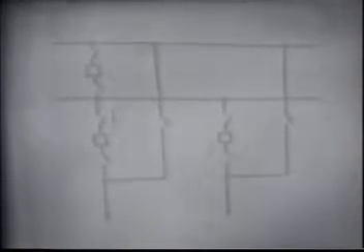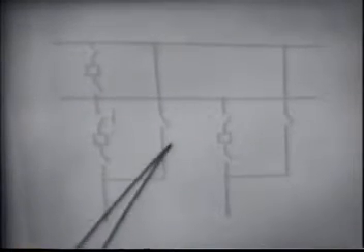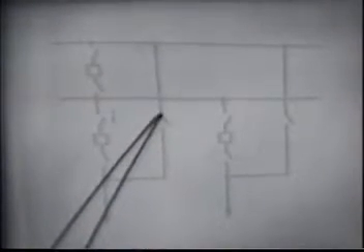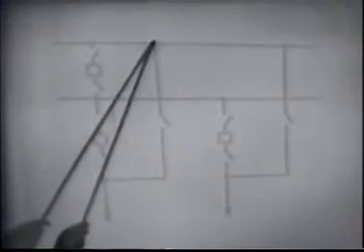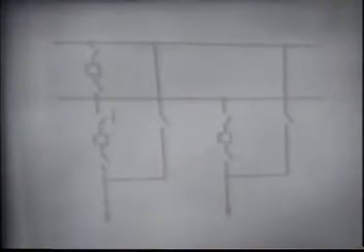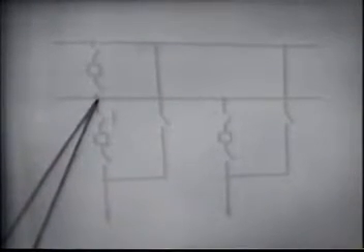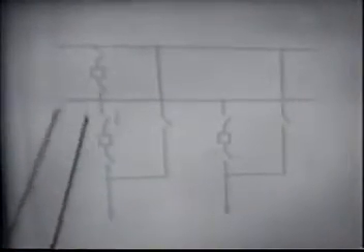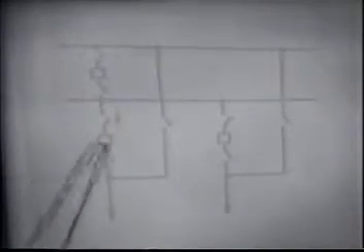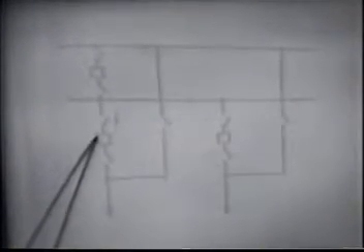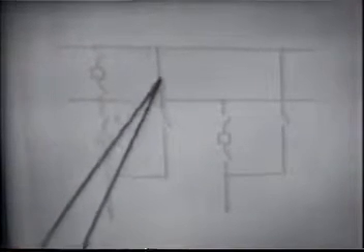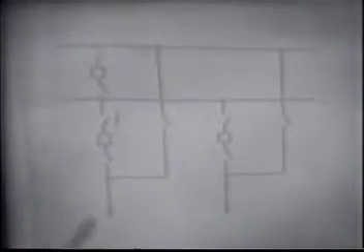However, to get the additional flexibility of being able to do maintenance on a circuit breaker, we've added a bypass switch or a switch connecting to another bus, an auxiliary bus. This bus in turn is connected to the main bus through a circuit breaker. So it is possible to take this main line breaker out of service but still have this as your path of energy transfer.